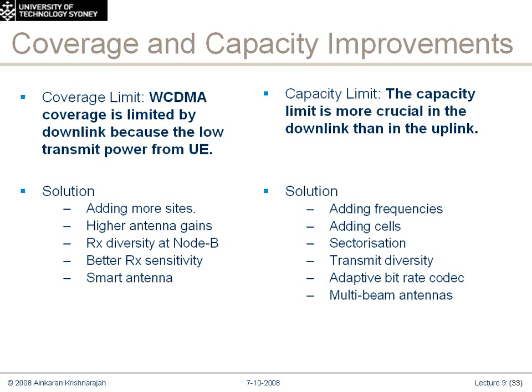So what you can do is, by changing the codec rate, you can actually drop the bit rate and therefore reduce the requirements on the base station for sufficient power to run a service, and therefore squeeze more users in. So that's kind of the approach.